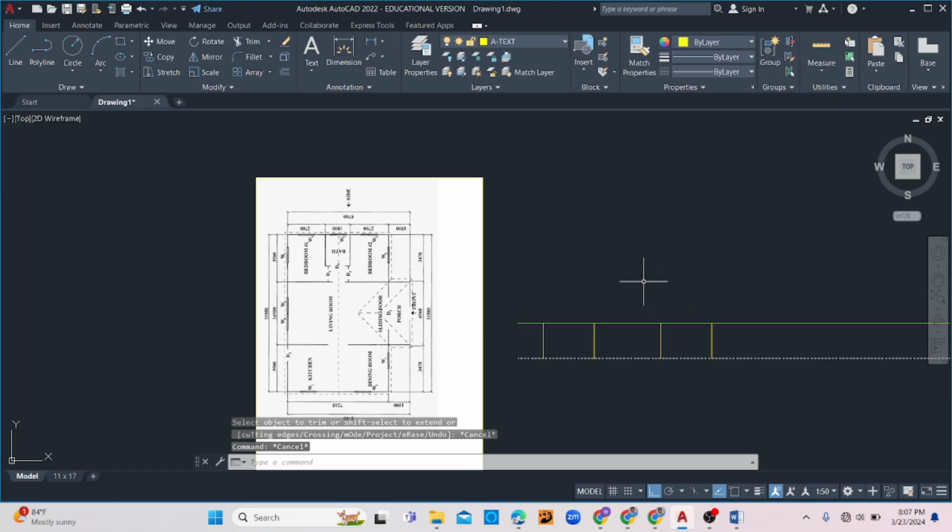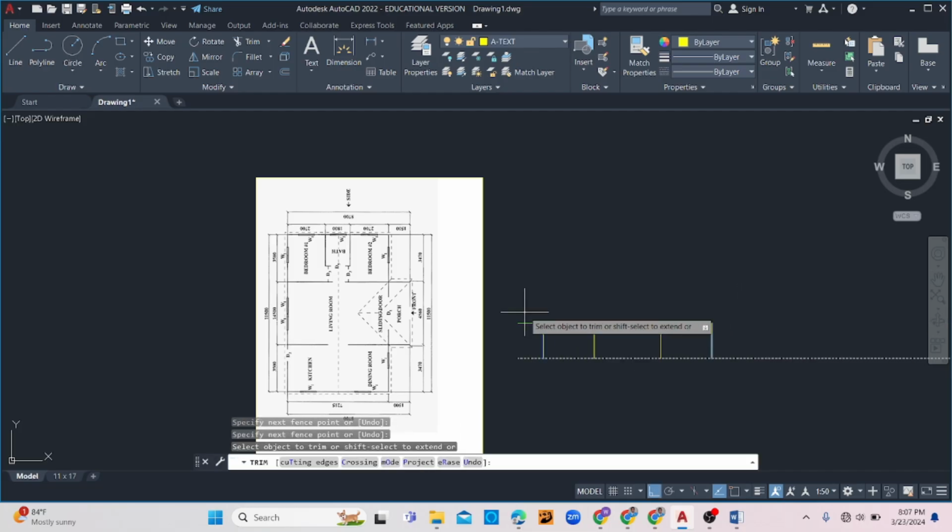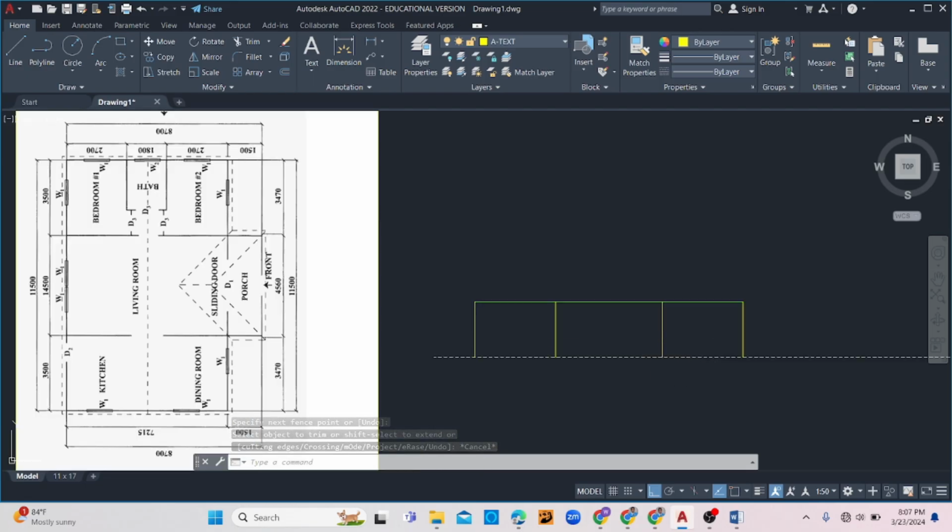And then I'm going to be adding my roof now. Alright, I'm going to be drawing my roof. Now they have already told me that the overhang for my roof is 300 millimeters. So I know everywhere there is an edge, as you can see from the roof plan here, the overhang where the building extends beyond the wall is 300. Everywhere there is an edge, you know there's going to be one because the roof is covering that portion. So what do I do? I offset these wall lines here by 300 millimeters.